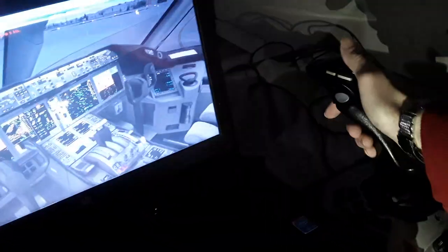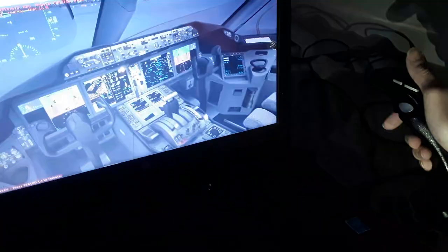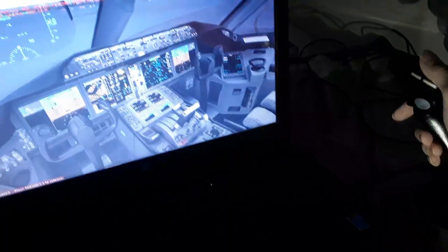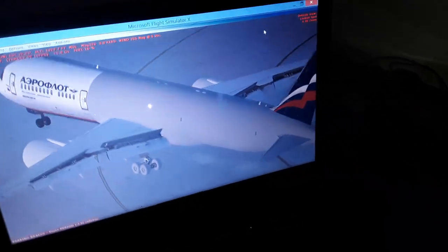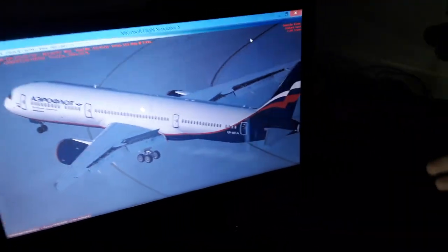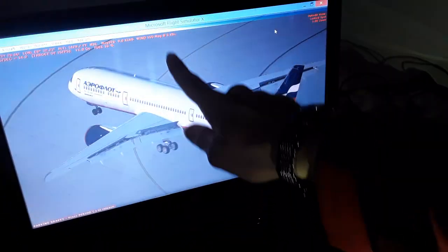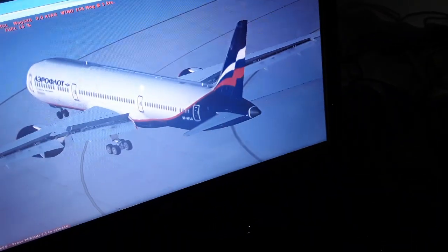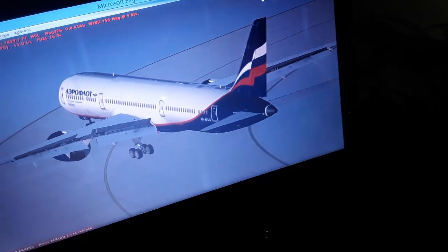We push the side stick or the yoke down, and we apply as much thrust as we need to exit the stall condition, so thrust with the engines forward, as you can see. You can also see here that we have the center of gravity, which is where the yawing axis of the aircraft is. For the yawing axis, you use the rudder to yaw either left or right, like this. I have it on my side stick, left and right rudder turns.